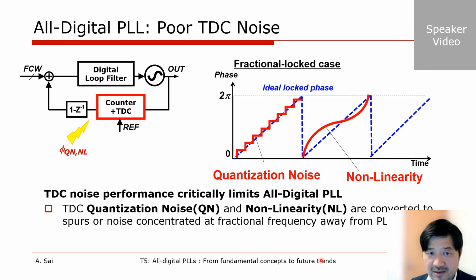However, all this benefit is built on the assumption that the time resolution of the TDC is sufficiently high. The TDC performance, especially quantization noise and nonlinearity, critically dominates that of the ADPLL.